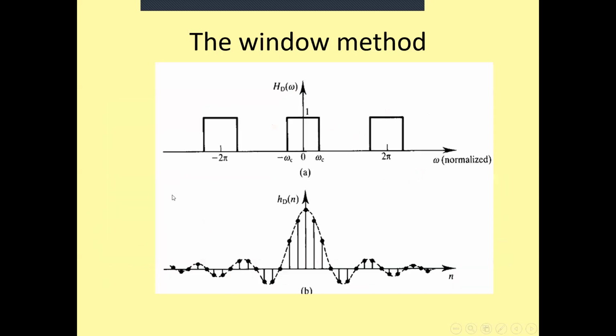Look, please. Now, this will be the figure I'm talking about. Well, this will be the low pass filter. Its cutoff frequency band is from 0 to omega c, and minus omega c to omega c will be the double side spectrum. Of course, if you are going to draw a single side spectrum, at that time it will be from 0 to omega c, but most of the time we are talking about the double side spectrum for analytic operations. So the filter will be ranged from minus omega c to omega c, and its magnitude equals 1.